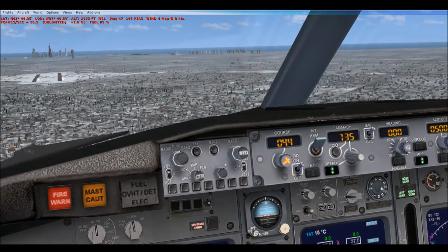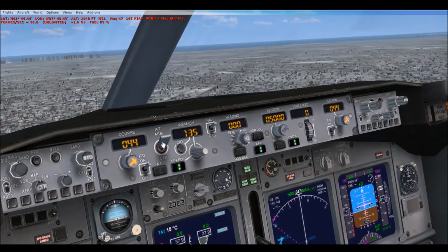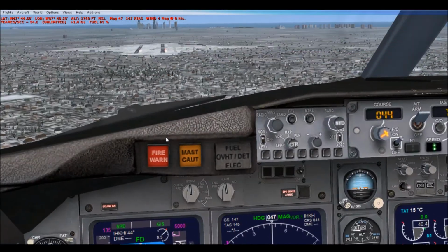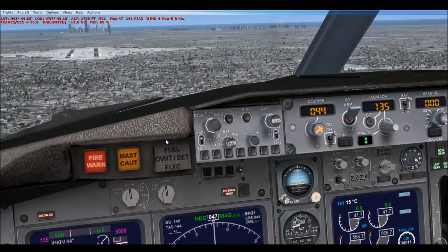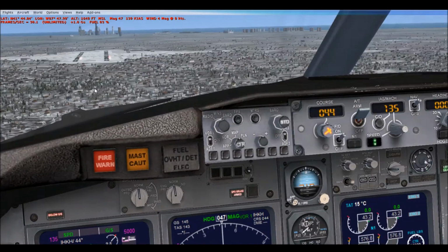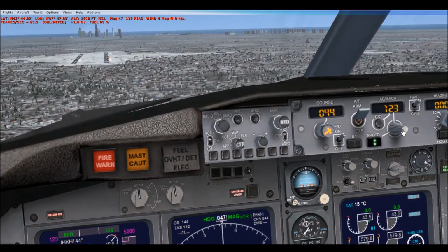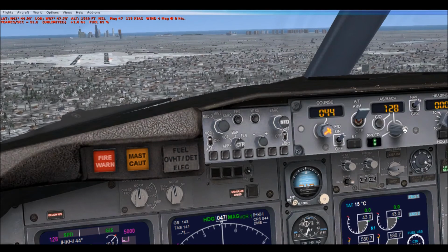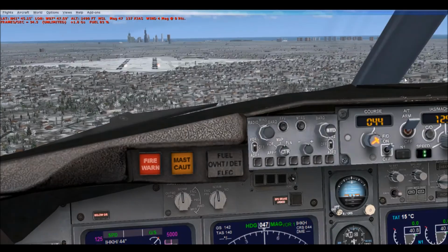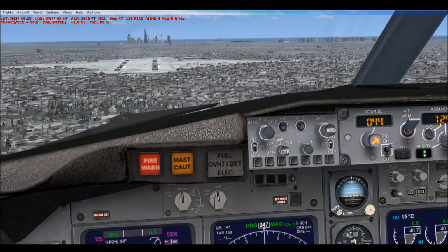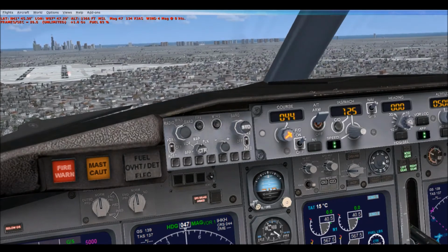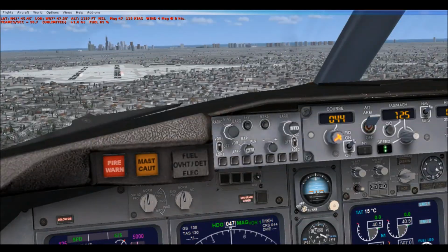So right before we touch down, what you are going to want to do manually is shut the auto throttle off and then pull the throttle all the way back on your own, because we need to cut off that speed. We want to touch down with the throttle at 0, ready for the reverse thrust to deploy. Go ahead and keep on losing speed. Now you can turn the auto throttle off by just pressing this, or Shift and R at the same time. That's the keyboard shortcut for the auto throttle off.